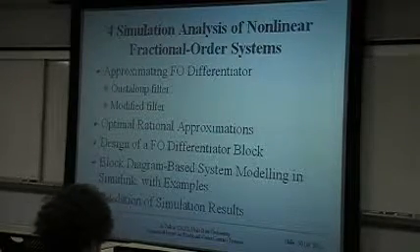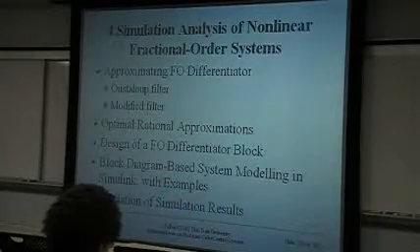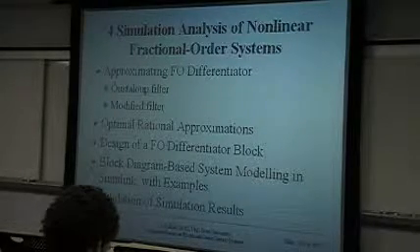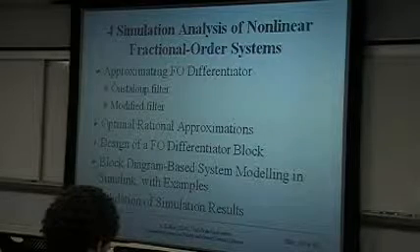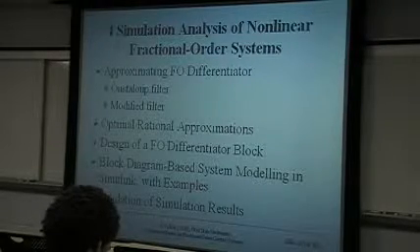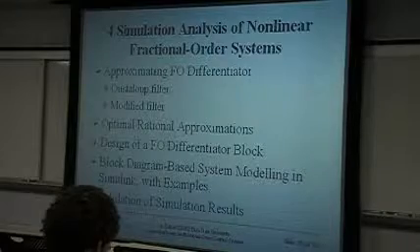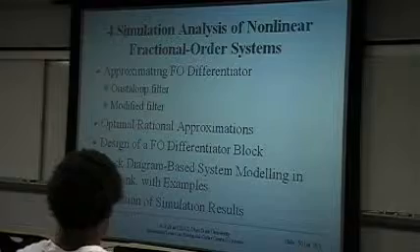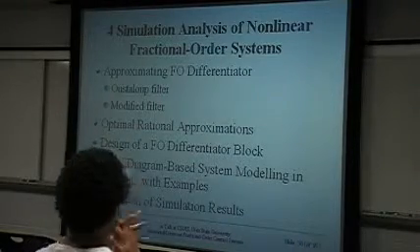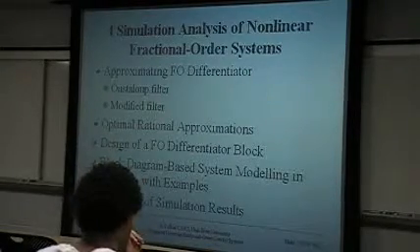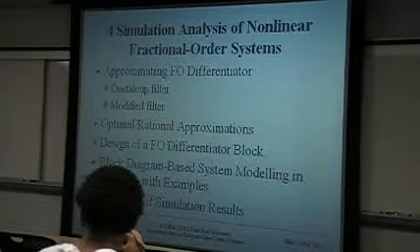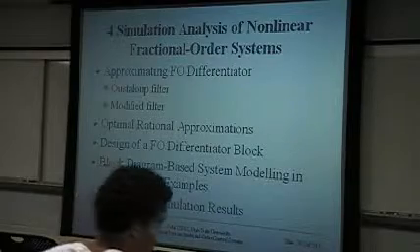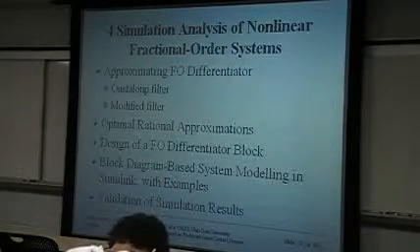And if you approximate the original fractional order differentiator, then you may expect to get a transfer function of very high order, usually 40th order or even higher for certain systems. So for those kinds of systems, we may consider optimal model reduction to fit the original fractional order transfer function by the use of low order integer order transfer functions.